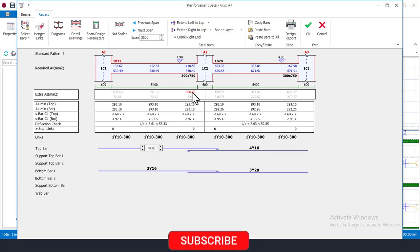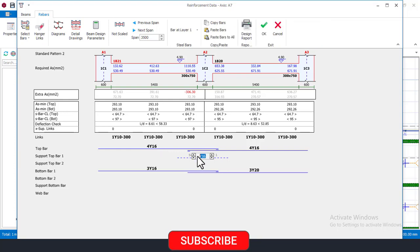Now, since there's a failure at this place right now, I'll now introduce a layer 2 support reinforcement. I'll come here right now and add it up to at least make it 2 or 3 numbers of Y16. And then before I do now, once you're introducing a layer of reinforcement, you must assign it to be at layer 2. So I'll come here right now and put bar at layer 2. Okay? Now you can see that it is now okay.